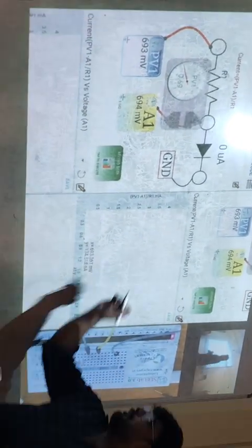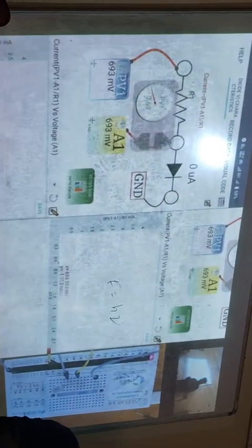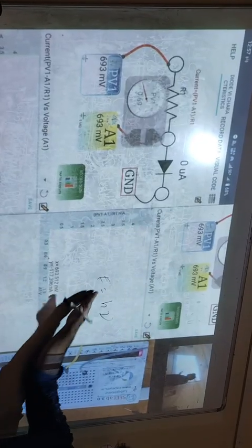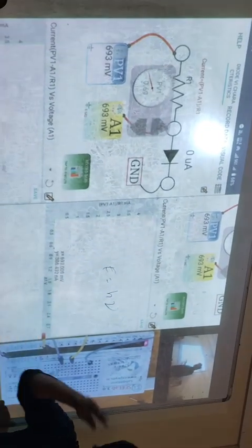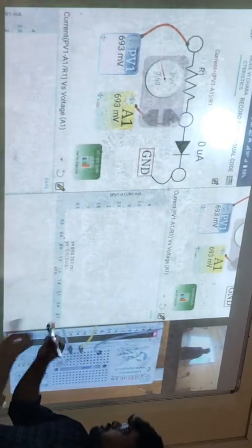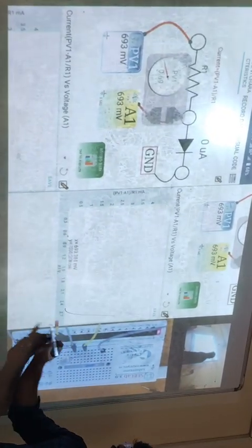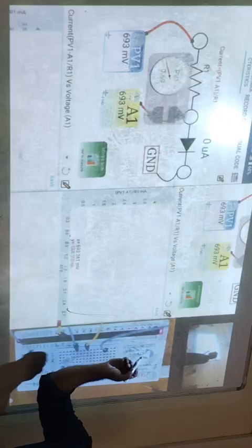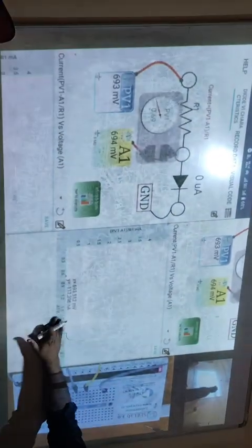So you are familiar with E is equal to h nu. So blue is a higher energy, higher frequency, right? So you need higher energy, therefore you need a higher potential difference to jump this band gap. So blue is going to be somewhere here. White is also going to be somewhere here because white LEDs are a combination of blue and phosphor. Okay? Red will be somewhere here, green will be here, etc.